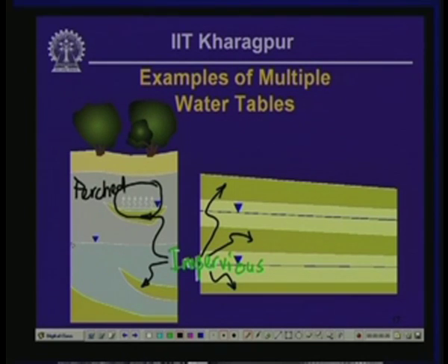You can have another groundwater which is exposed like that, which has got a surface below the surface of the zone of saturation, or water table, like that. So that is called an unconfined aquifer actually. So this one is an unconfined aquifer.